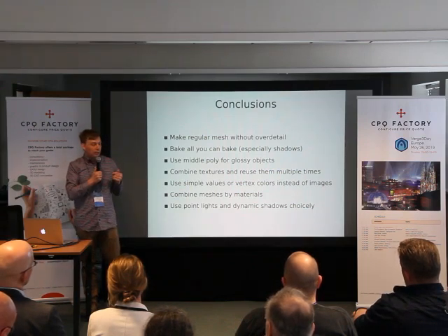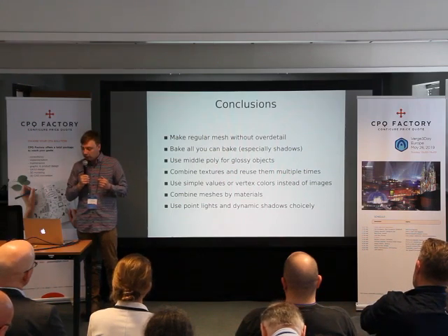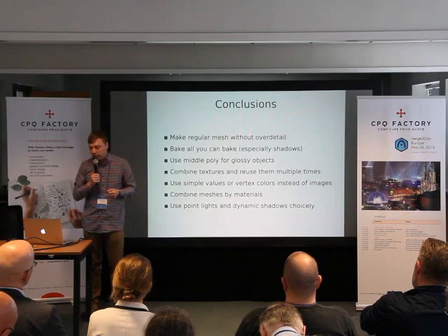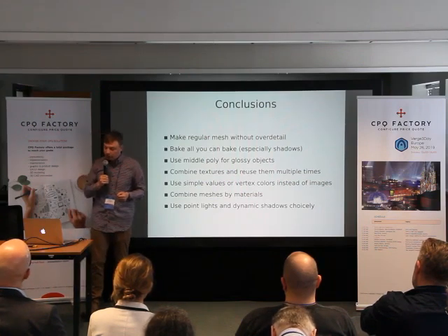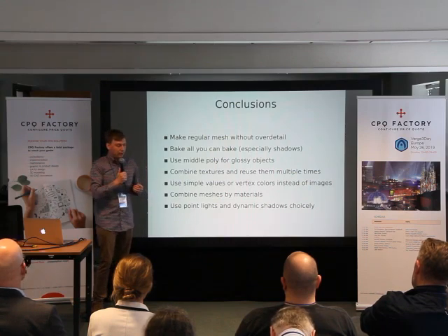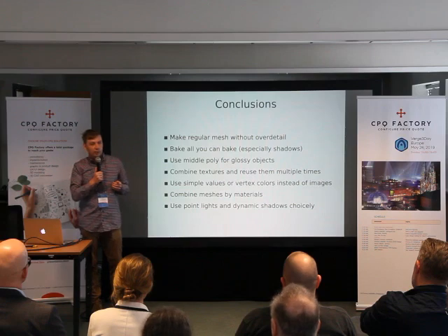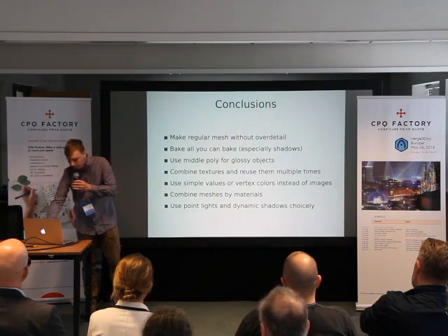This will save a lot of texture space and a lot of loading time for the application. Combine meshes by materials, and use point light, dynamic shadow, and any other post-processing judiciously, only if it really helps you to show the product from a good side.